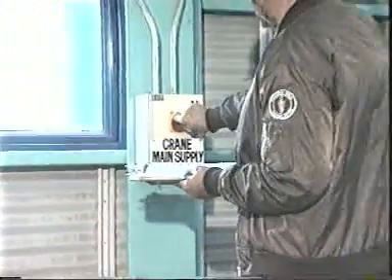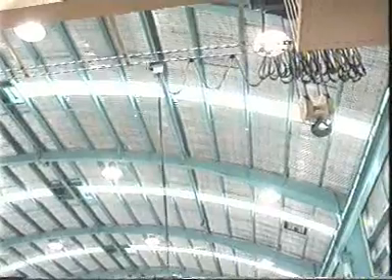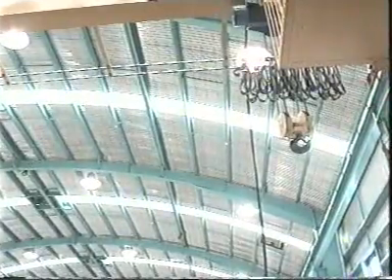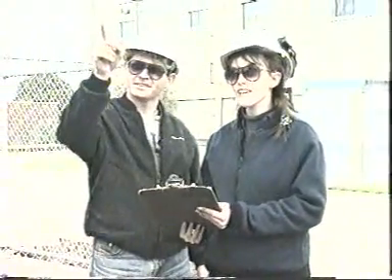A full shutdown will of course involve turning off the main isolator power supply and securing the unit. Remember to position the crane in its correct parking area and clear of any obstructions. Before going off duty, you should notify your supervisor about any irregularities concerning the operation of the crane.